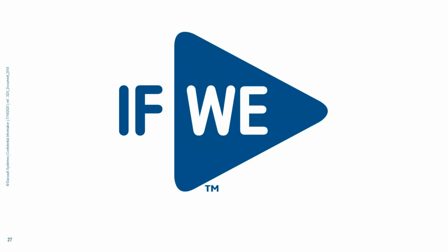the machine itself, right? It's already got information in there that you don't want to change. So anything updated, there are options in the software that if you do go to number new wires, there is a checkbox essentially that it will not remove or update anything that's already existing in the software. So if you've already built your schematic with certain parts, it will not change any of that information in there. Yep, definitely. So yeah, it definitely understands and gives you the opportunity to not modify anything.